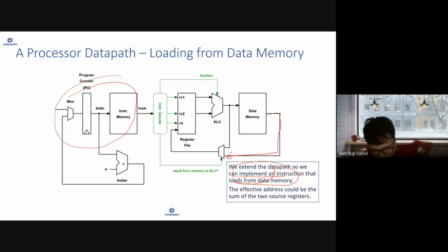Okay, so there is this instruction decode. Now the result should come from the ALU, or it can come from a memory. Sometimes you directly want to access a memory, and the memory address gives the result. Maybe you're doing address addition and you want to read from a memory. There the result can also come from the memory, and this will be decided by your instruction code.